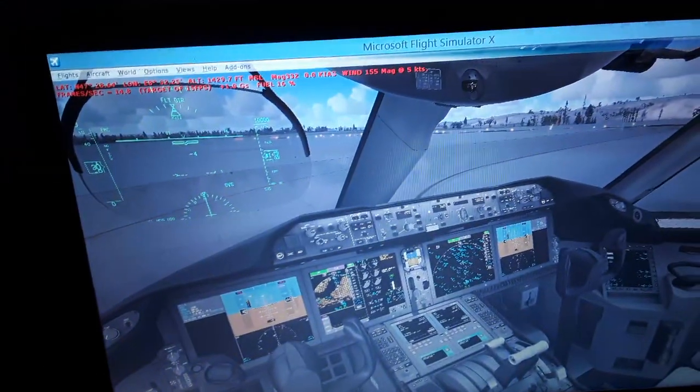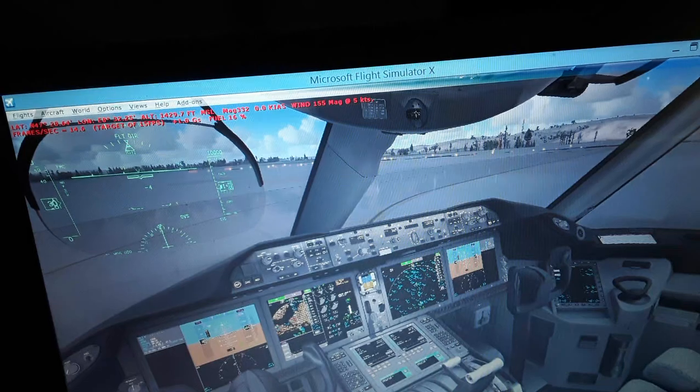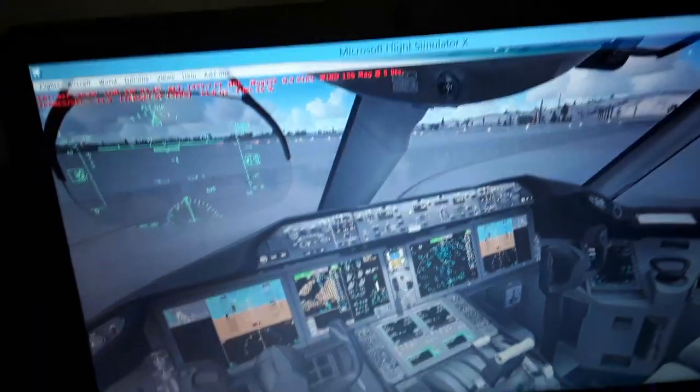We have the LSZH localizer of the instrument landing system that receives the radio frequency transmitted from the airport threshold antennas, so we can receive the radio frequency from the onboard antennas of the aircraft and align the aircraft with the magnetic heading of the LSZH localizer, the horizontal localizer and the vertical glide slope, so we can align and land using the instrument landing system.